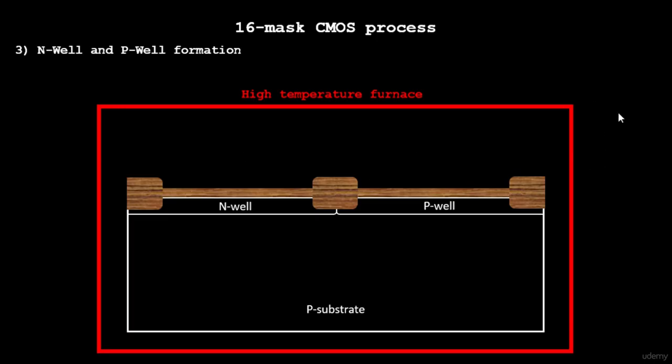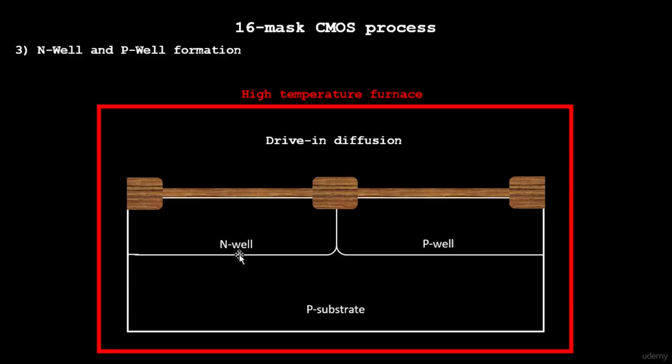So this area and this one are your active region, where you actually grow your transistors, and the isolation region will protect this transistor from communicating with this transistor. So you have actually created an electrical isolation over here. Okay, so what we'll do is we'll stop at this point.